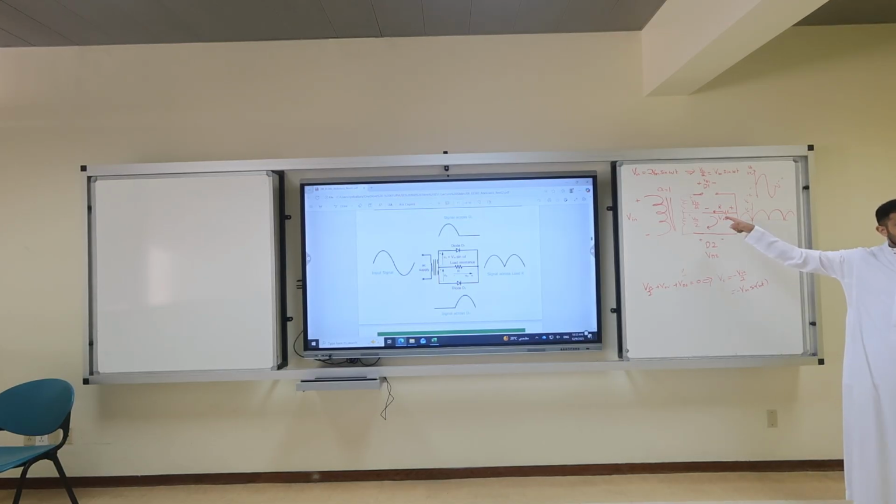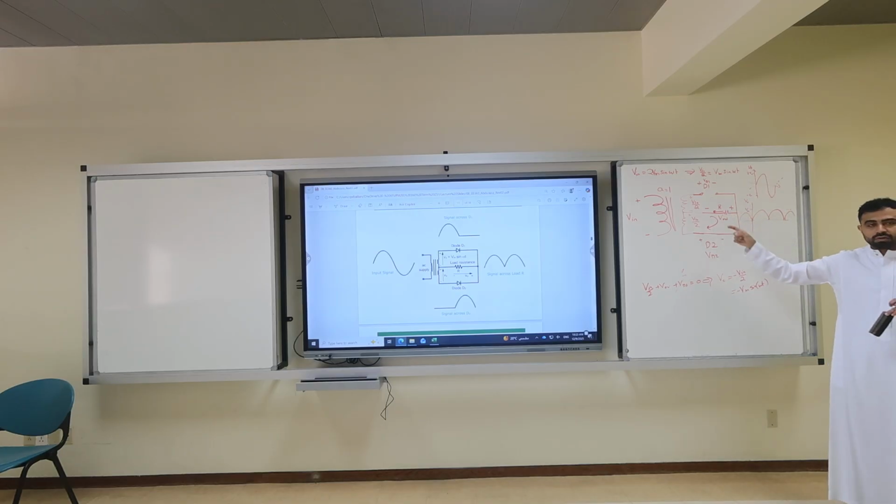Watch the YouTube video. Try to do numbers. The current is from here to here, from positive to negative. It's V output over R. That's it. The resistance is 10 ohm. This output will be square root of 2 times 110 over 10 ohm sine omega t. Single phase, not three phase. Okay?